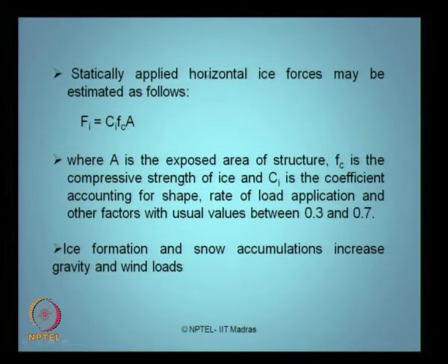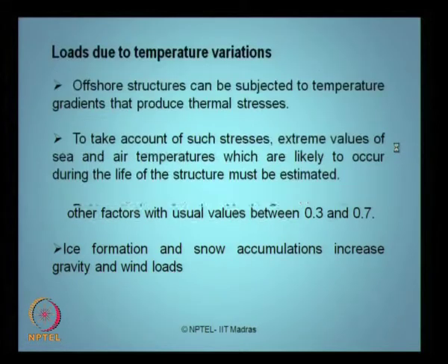Now, statically applied horizontal ice force may be estimated from the given equation, where in this equation A is the exposed area of the structure, Fc is the compressive strength of ice, and Ci is the coefficient accounting for shape, rate of loading application and other factors, which usually has values between 0.3 to 0.7 as seen in the literature. The ice formation and snow accumulations increase gravity as well as wind loads coming on the offshore platform.